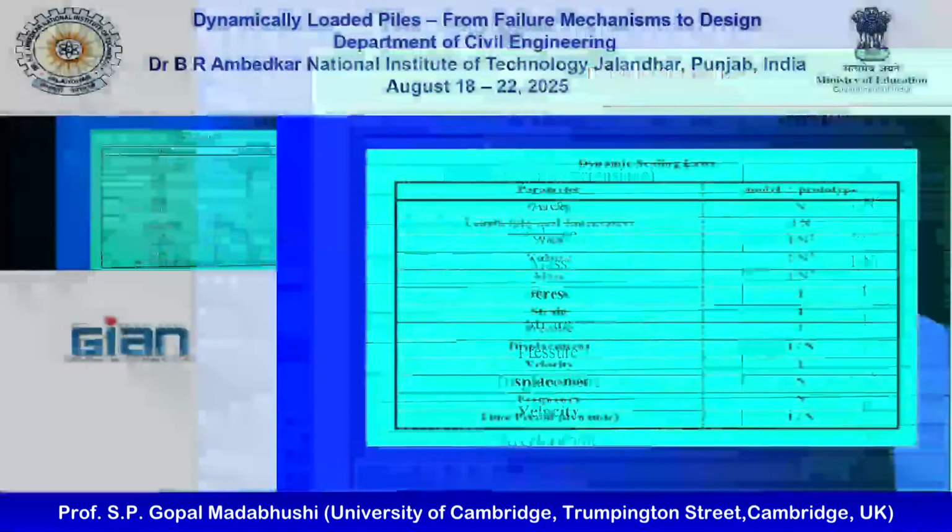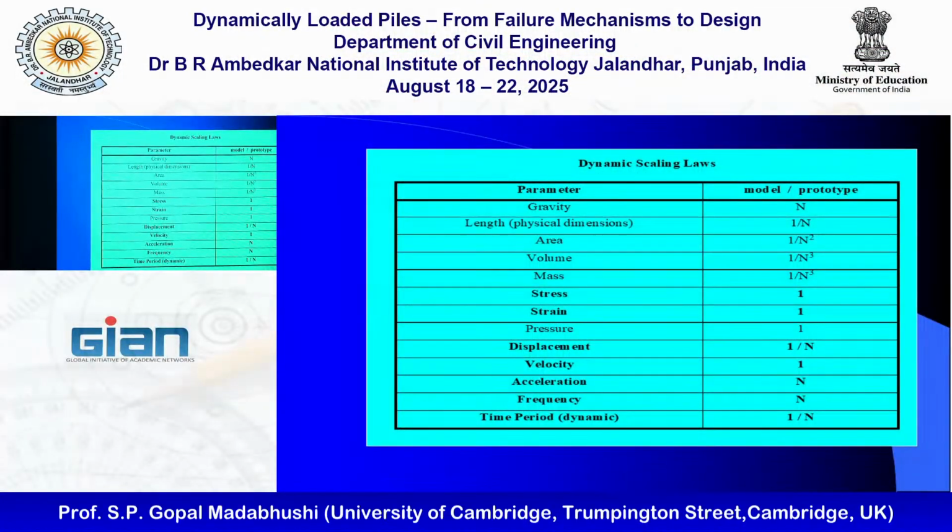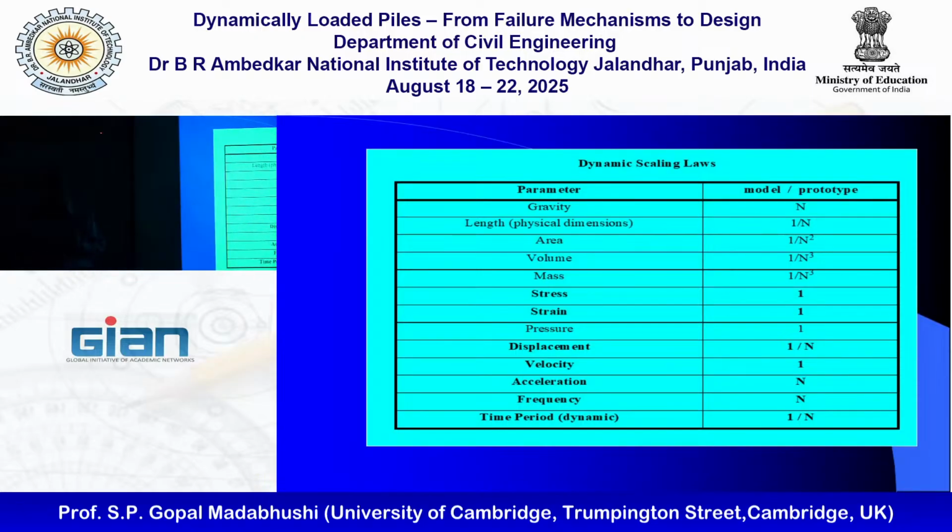Normally, earthquake motions will be there, and sinusoidal waves will be used in the lab. Can I make it using any other method, equivalent to earthquake motion? Yeah, I need to increase the amplitude of the shaking by a factor of n, because acceleration should be n times larger and the time scale should be n times smaller.